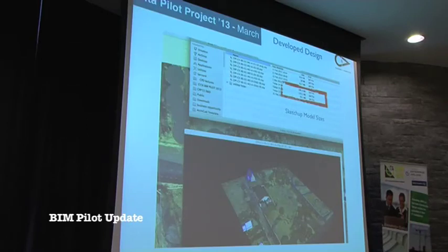And this is just a very quick test. Here you can see we saved it into a SketchUp format. We have the full 3D models of the trees. It was 300 megabytes. We simplified the trees, and the file size was then 150 megabytes, so it's half the size. And then we end up with very simple trees, just like bubbles and mass. So we end up again with 70 to 80 megabytes. So just to say, the model can be very, very big when you export it in full detail, but it can simply mean as well that some elements may be overly detailed in your design model.